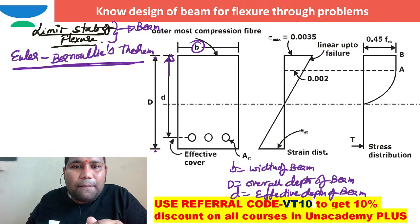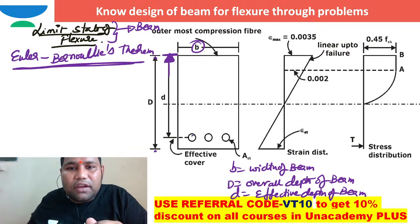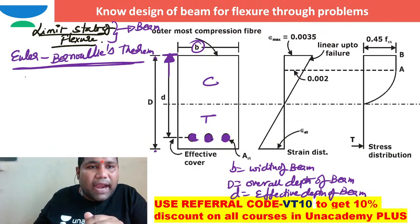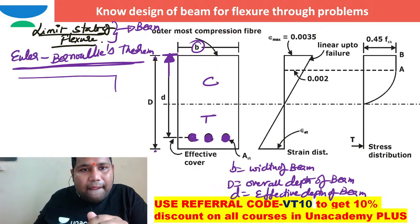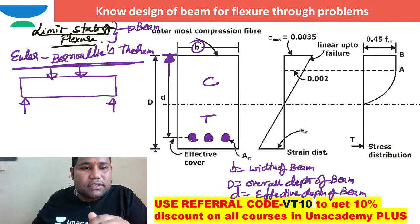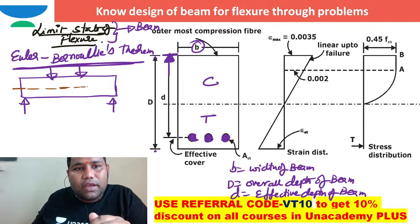How can you define this effective depth of the beam? It is the distance from the extreme compression layer of the beam to the center of gravity of this steel, which is the area of tension steel. This is the compression zone and this is the tension zone. If I apply transverse loads in this way, the tension is on the bottom side. The neutral axis is somewhere here, with the compression side above and the tension side below.